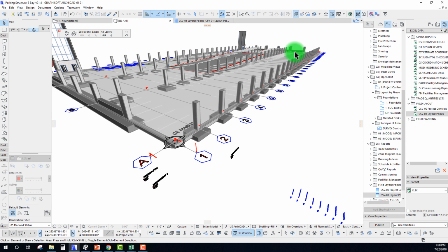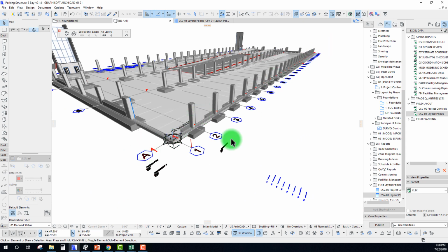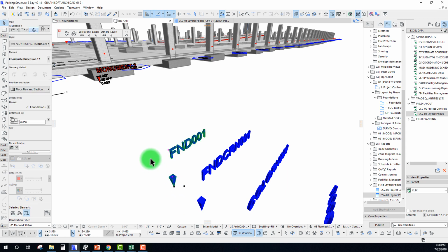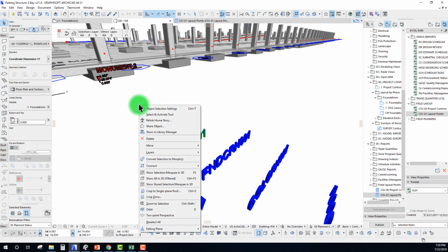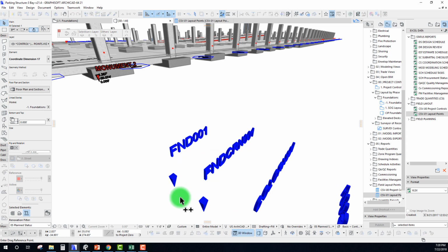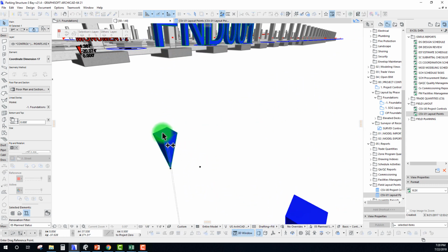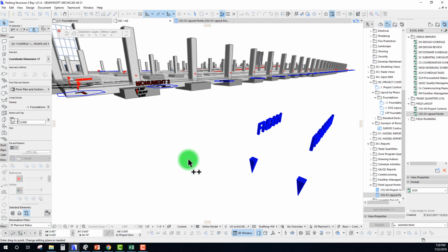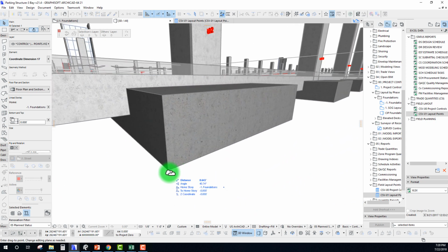So, okay, with that, let's go ahead and add in points for this A line right now. We'll just add all the footings in real quick. So what I could do is grab my foundation 01 and do a move and drag multiple copies. And the point that we always have to be moving these around by is the point right at the bottom of the cone there.